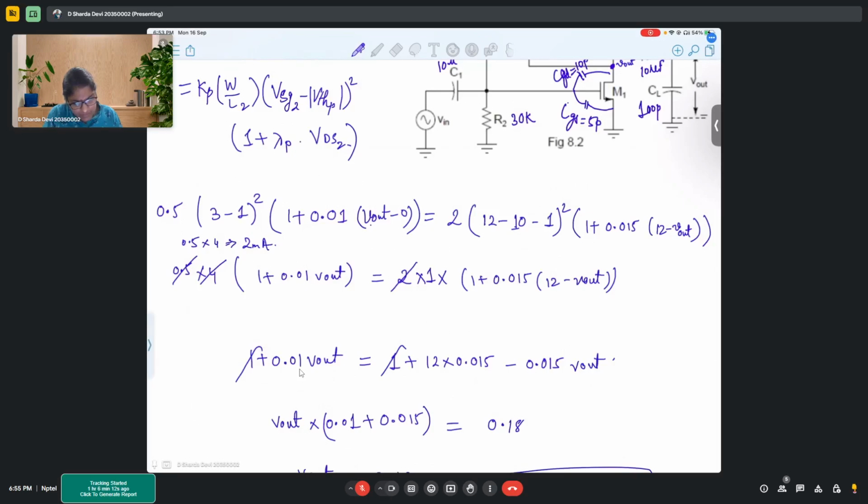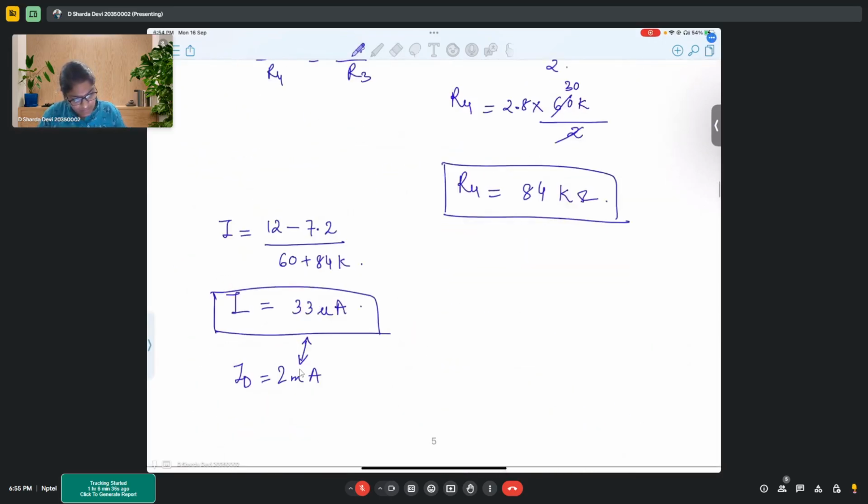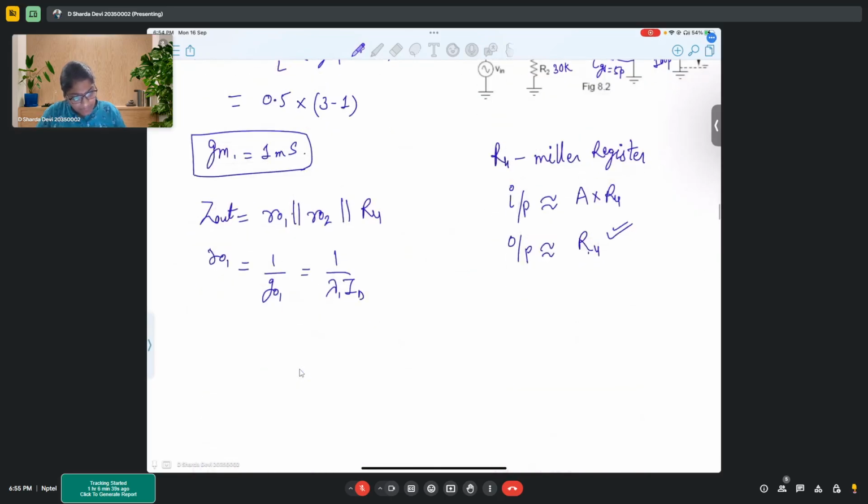No, but still, that would make it more, point 1.24. Isn't it 2 milliamperes? How much is coming from here? 2 into 2 minus 1. Yeah, it's 2 milliamperes, right? Okay. Yes, ID1 is 2 milliamperes, because I made some mistake. Anyways, ID1 equal to ID2 is almost equal to 2 milliamperes without considering channel length modulation.